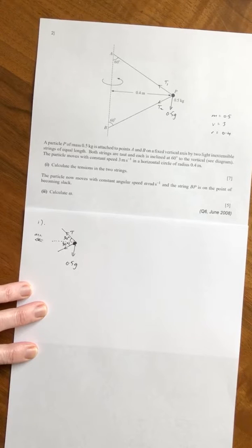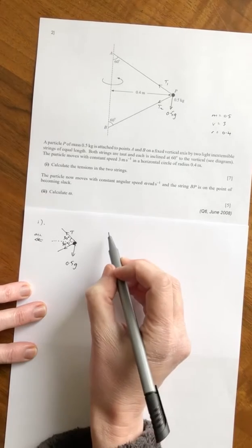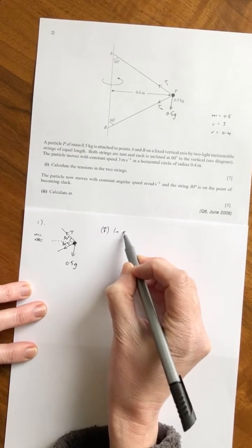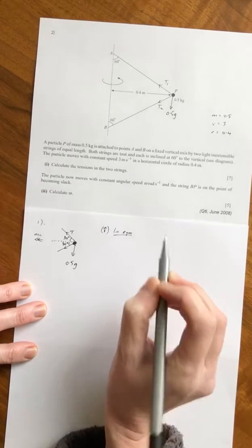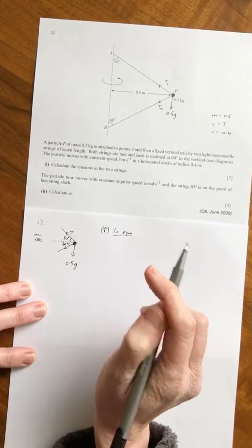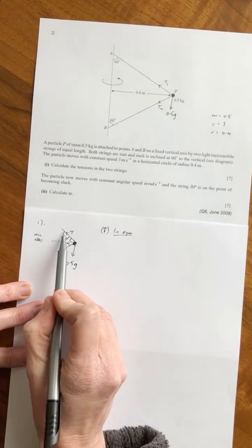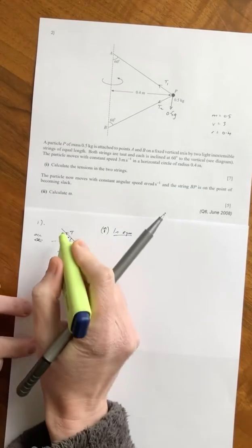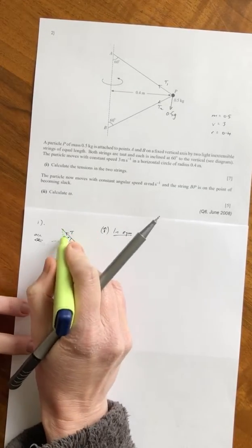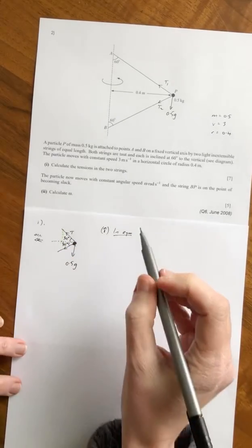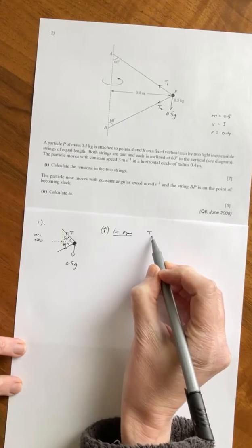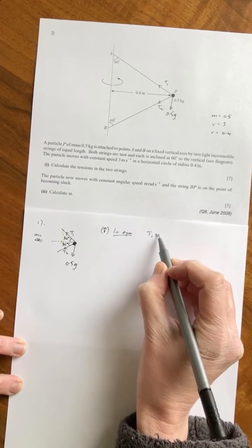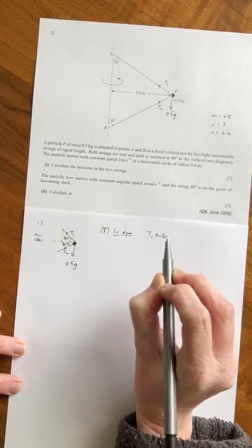Okay, 2 different directions, vertical, horizontal. It's always easier to deal with the vertical first if you can, because of course it's in equilibrium. If it's in equilibrium, I know that forces up equal forces down. So forces up, well, I've got that vertical component of my tension force. So my tension force here, it is opposite the angle, so that is the sine component. So I'm going to have T1, sorry, I didn't mark on T1, T2. I'm going to have T1 sine 30. That's the only force going up.